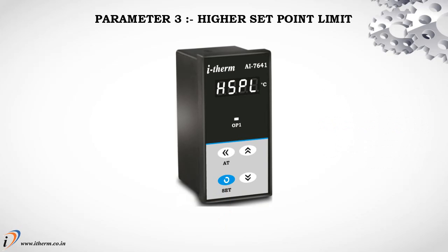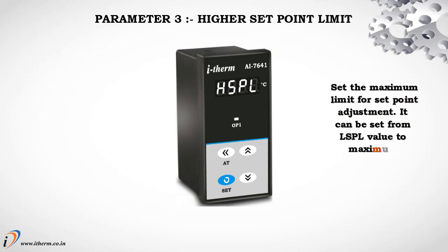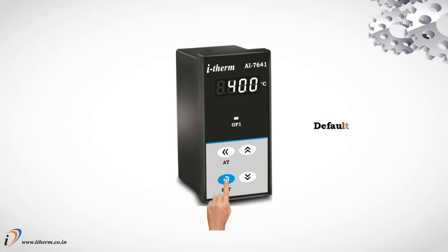Parameter 3, higher set point limit. Set the maximum limit for set point adjustment. It can be set from the LSPL value to the maximum specified range of the selected sensor. Default HSPL value is 400.